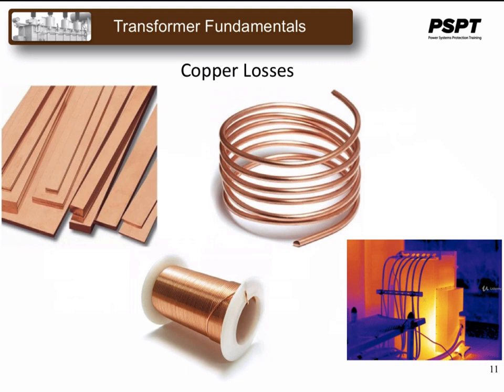A transformer's rating can be increased by better design and transformer construction to reduce these copper losses. Transformers with high voltage and current ratings require conductors of large cross-sectional area to help minimize their copper losses. Increasing the rate of heat dissipation through better cooling by forcing air or oil, and or by improving the transformer's insulation so it will withstand higher temperatures, can also increase the transformer's rating.